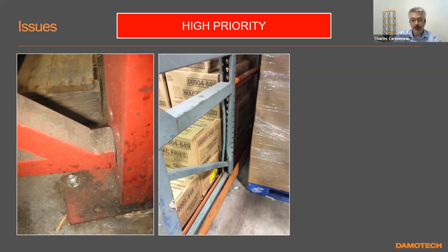Yeah, it still has some capacity, but in order to stamp it and say, yeah, you're good to operate, you're safe, and put my name on it, I'd have to take it out of there, put it under a press, probably destroy it, and then tell you, yeah, you were right, for your 2,000-pound pallet, it was okay. But this was originally designed for 2,500 pounds or a 3,000-pound pallet.